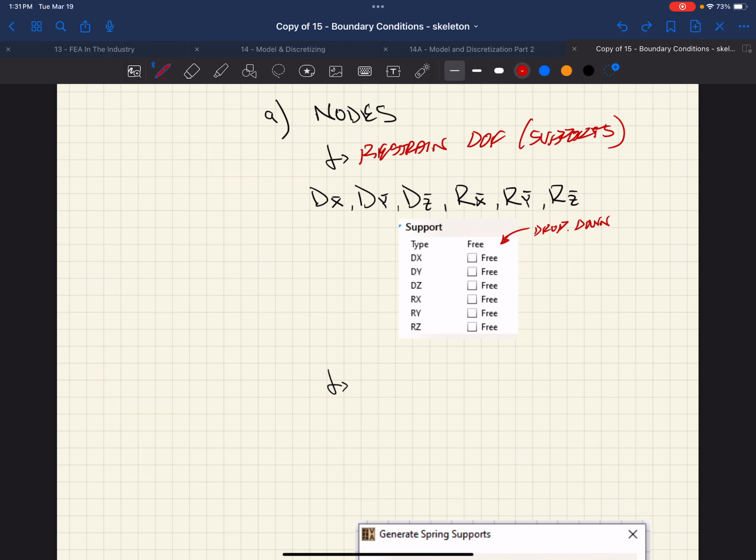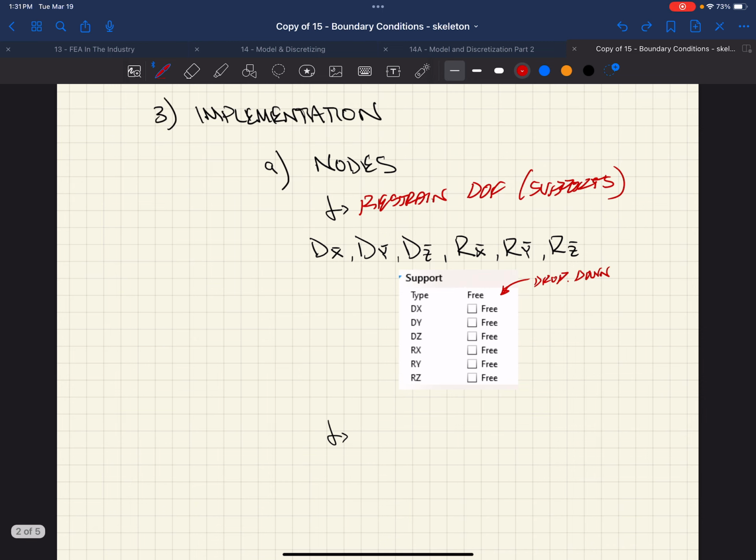That being the case, with these being supports, and I mentioned before, with foundational supports, a lot of times the code allows us to, or we can at least rationalize that we can decide between this fixed or pinned support case. With a fixed, that means it is infinitely stiff. The foundation is infinitely stiff for rotation and translation. For a pin, it's infinitely stiff in translation.